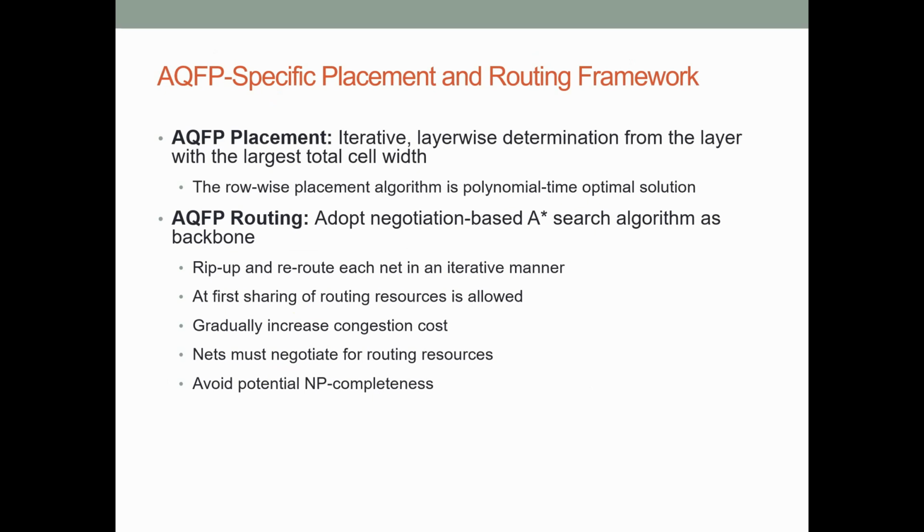Using the synthesis results, we can perform the physical design, including the placement and routing. We have developed an AQFP-specific placement and routing framework. For the AQFP placement, we use an iterative layer-wise determination, starting from the layer with the largest total cell widths. The row-wise placement algorithm actually has a polynomial-time optimal solution.